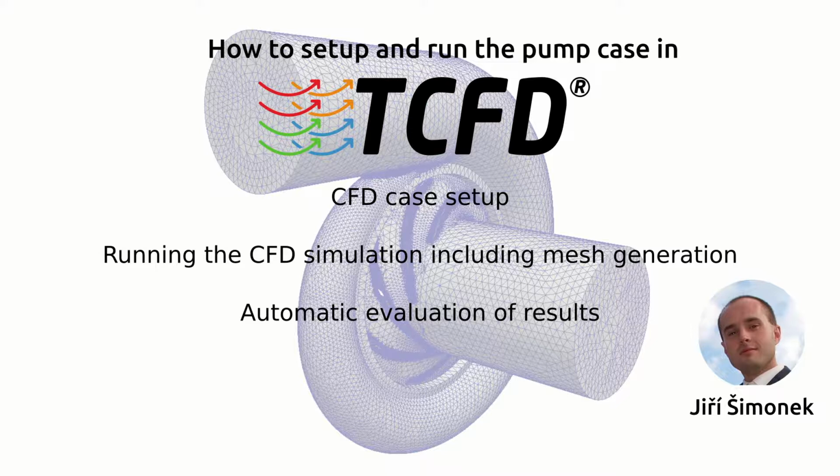And what do we need to start? The first thing we need is a CAD model of the machine we would like to simulate. Of course, it's possible to import an existing computational mesh, but I'll show you how to start from scratch with just a CAD model in an STL format, because Turbomachinery CFD reads models in STL.